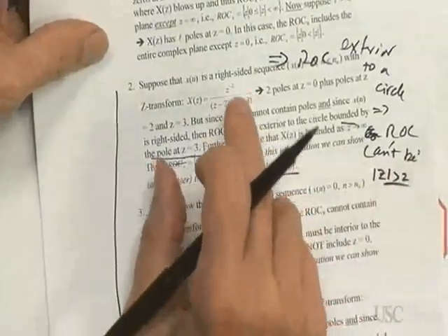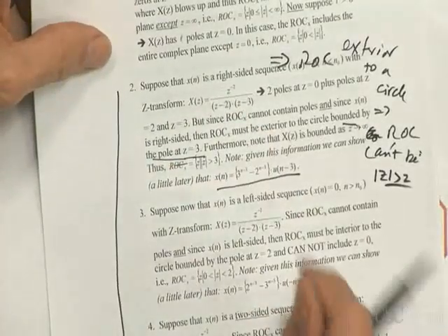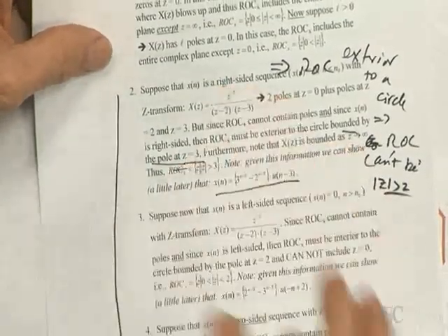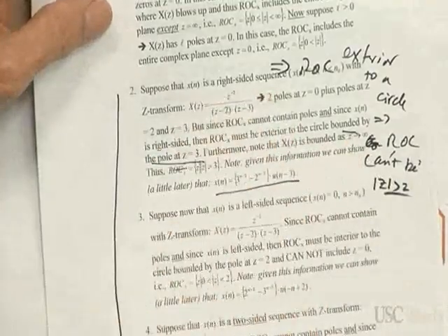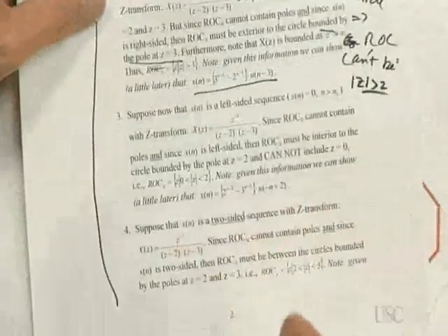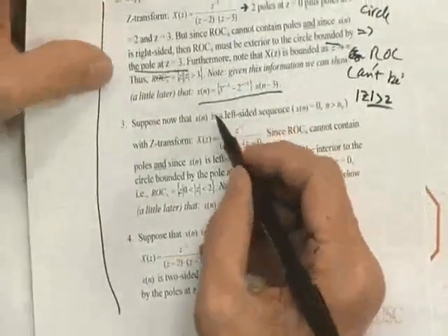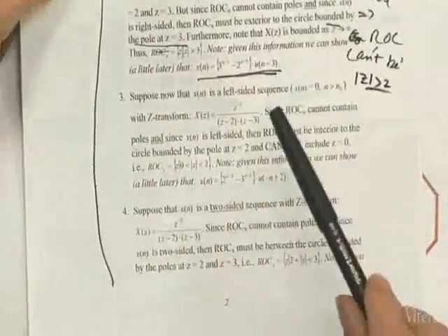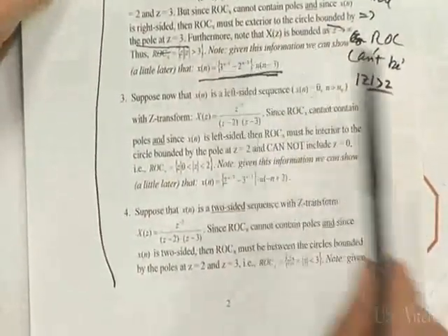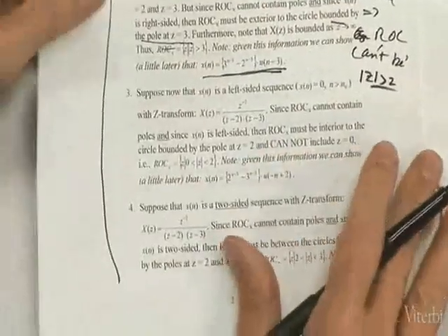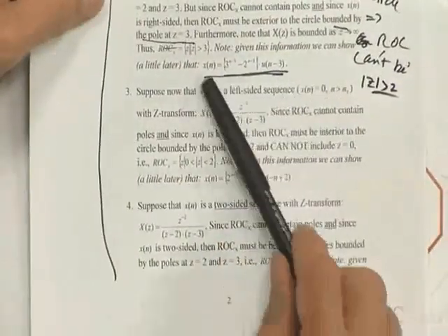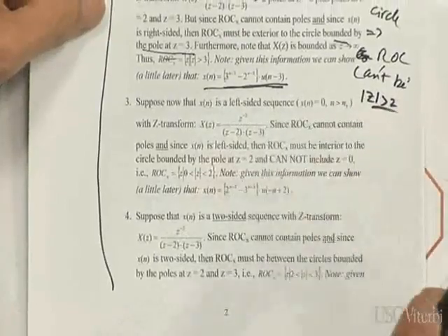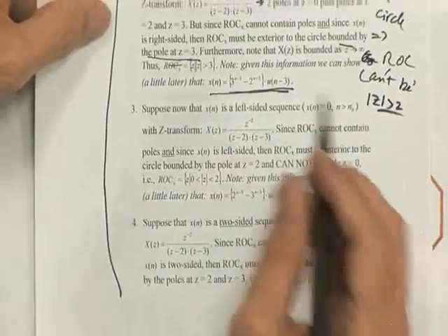So you know what I can tell you about the inverse z transform when you find it? It's going to blow up. The x of n is going to blow up. It won't be stable. Why? Because the unit circle isn't in the region of convergence, see? And sure enough, if you look at the result I'm showing you here, I'll derive it later, sure enough, it blows up. Blows up real bad.